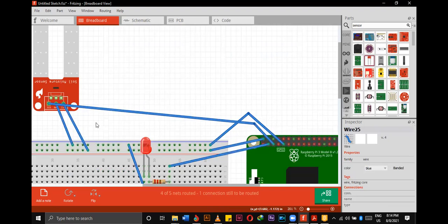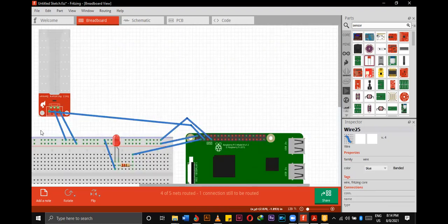So similarly we can use. Basically this sensor is used to detect the moisture content of the soil. If the soil moisture content is low, then it will provide the signal. After the signal comes, we can turn on the LED. If you can turn on the LED, that means you can turn on whatever components. Maybe you can obtain a pump, a small DC pump.